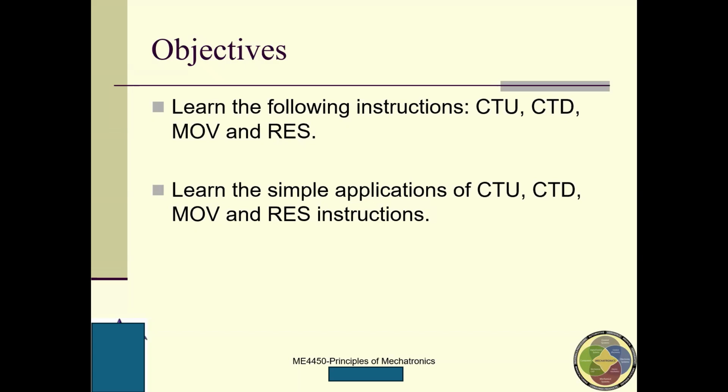So say CTU, okay, this is the timer. We have learned TON, timer on, and then we have learned TOF, the timer off. So these two guys are different, as Aiden answered. The difference is that TON is triggered by the false to true transition, the pulse. TOF is triggered by the true to false transition. Okay, so we know this difference.